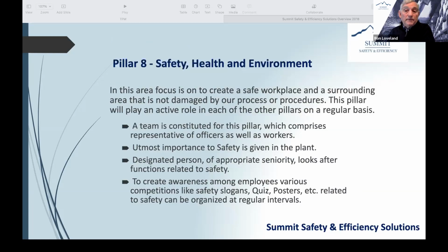And then finally, safety. Again, that's one of the pillars of our company. We do safety, quality, and industrial engineering. You've got to be safe. You've got to make sure that you have lockout, tagout procedures. Make sure nobody's working on the equipment when it's still live, electrically or mechanically. But you have to do the maintenance, right? So just make sure that you're doing it safely.